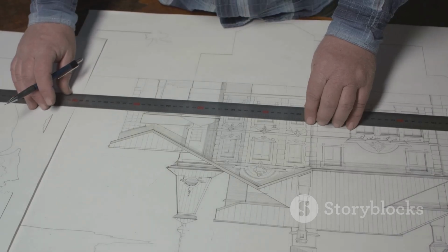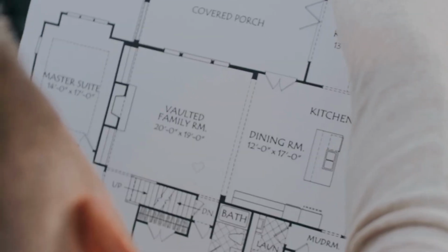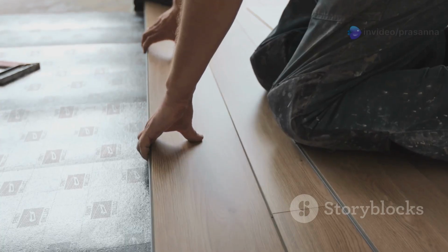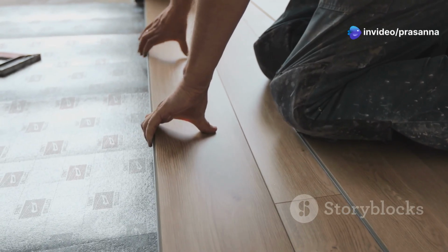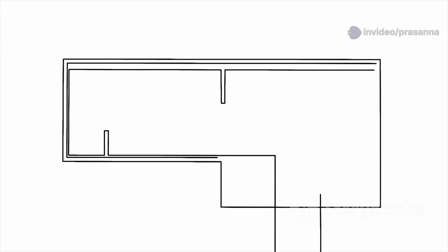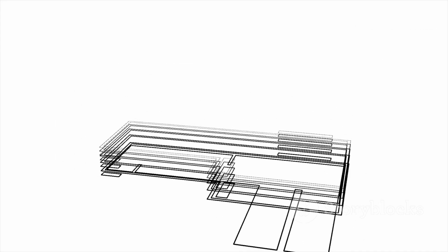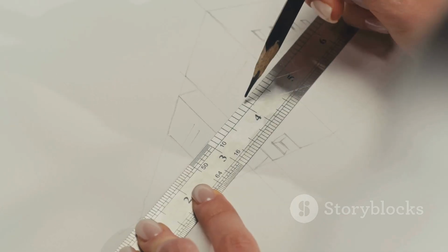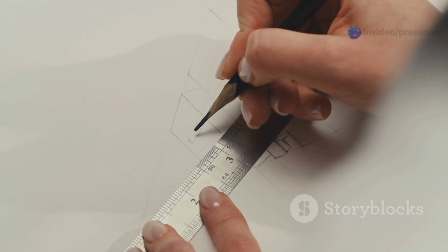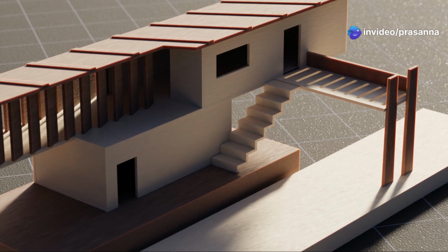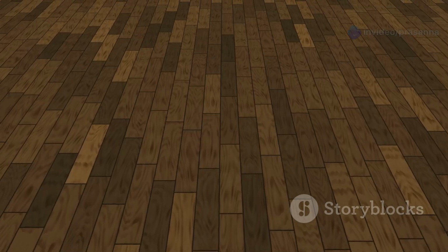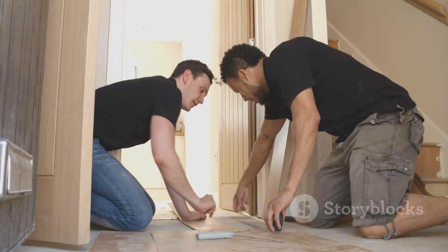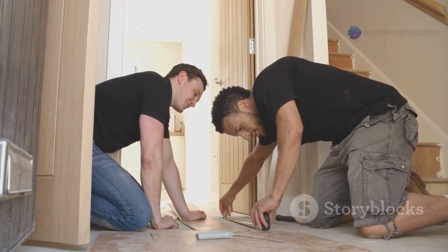Next, you will create the floor slab. The floor provides the base for your rooms. Similar to walls, you can create floors using basic shapes and the Push-Pull tool. If your ground floor plan is already a closed loop of walls, you might already have a surface created for the floor. If not, use the Rectangle tool or Line tool to draw the outline of the floor. Once you have this 2-dimensional surface, use the Push-Pull tool to give it thickness. This thickness represents the concrete slab or wooden floor structure. Ensure the floor aligns correctly with the base of your walls.